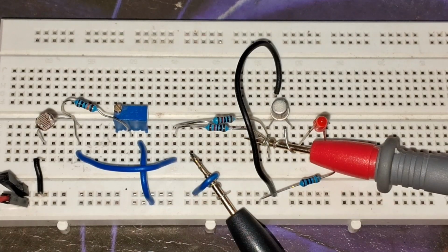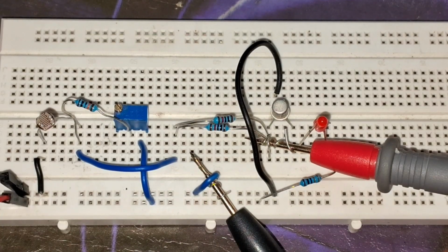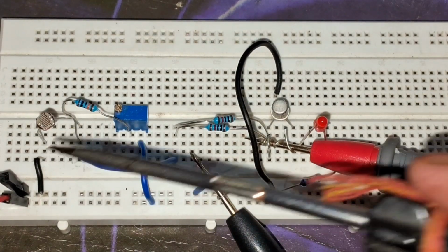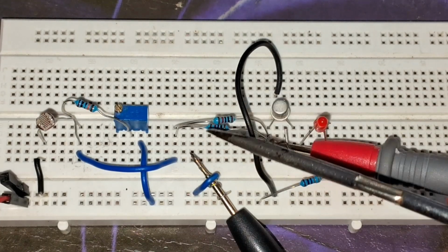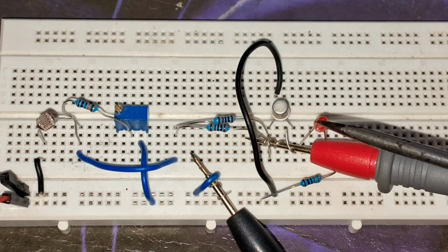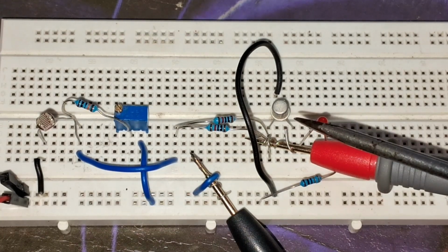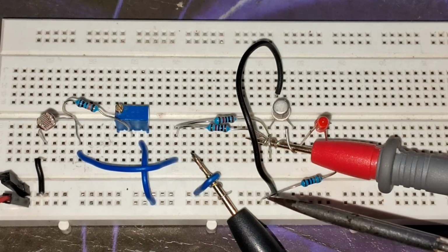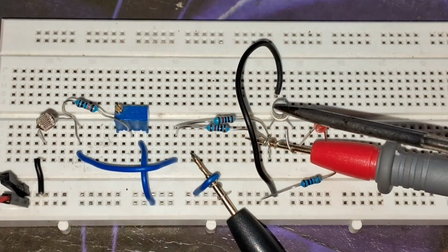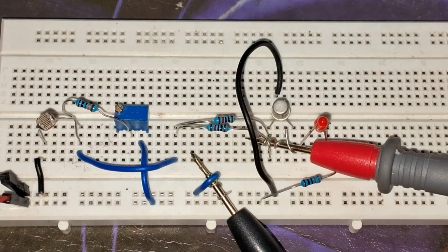Now moving towards the fourth experiment, which is an LDR based circuit. Here you can see I used the LDR, this potentiometer, and these are the base resistances. This LED is connected with the collector terminal, with a current limiting resistance, and the ground point is connected to the emitter of this transistor.